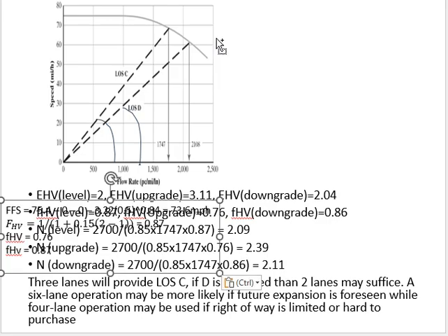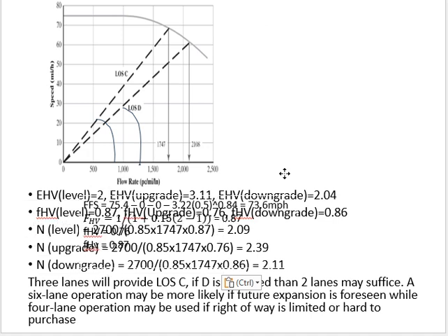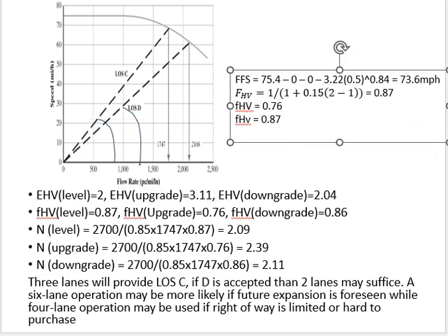We want a graph like this. This is something which you have to plot for your term projects as well. You will start from free flow speed. Your first point is free flow speed. Y-axis speed, x-axis flow rate.